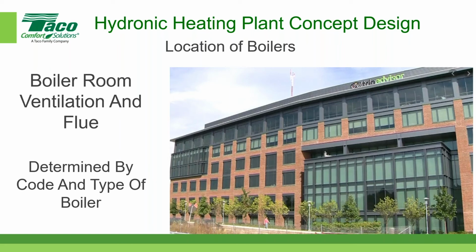And then the flue itself generally is going to be dictated by the boiler manufacturer. So whatever boiler you ultimately choose to put inside your building, work very carefully with your boiler manufacturer's rep and find out precisely what type of flue system you need for that boiler. And they vary depending on whether they are condensing boilers versus non-condensing boilers and a whole range of options. So check out the code requirements for ventilation and flue, and also check with your manufacturer's rep for boilers to find out what they also recommend for the specific type of boiler that you're interested in.